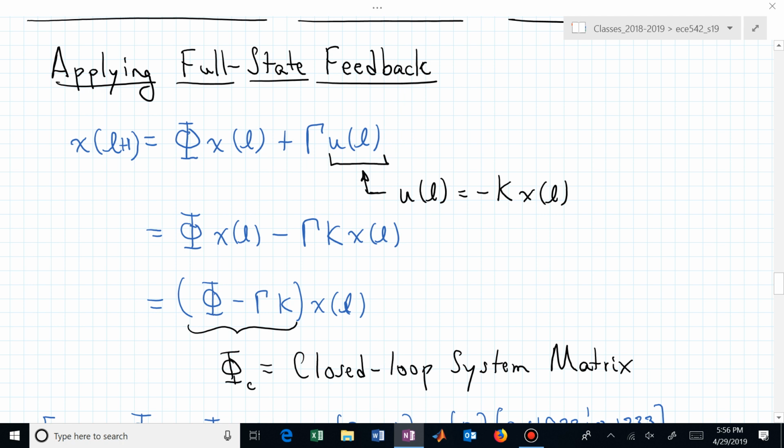If gamma was controllable through its first column, you could place the poles wherever you want with just the top row of K. Now you have a second row, or you now have some flexibility. Now maybe you can shape the eigenvectors of this phi minus gamma K. So there are different questions that now become answerable or askable when we're in a multi-input, multi-output setting.